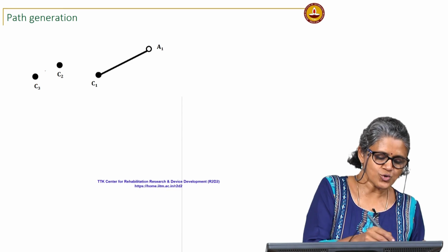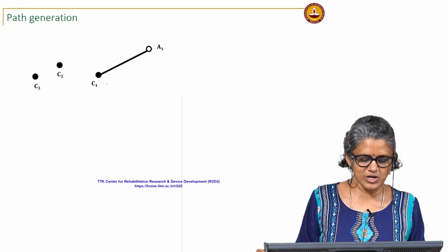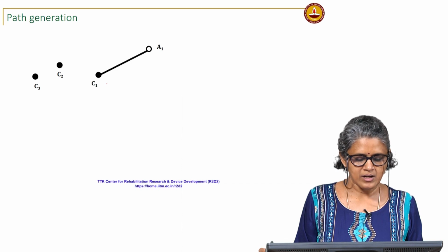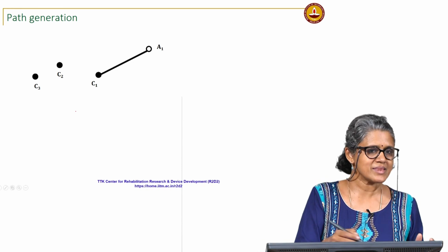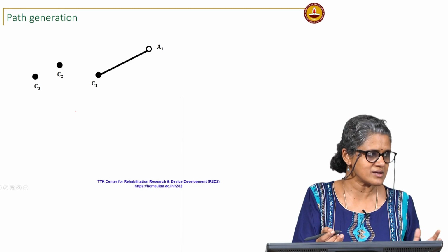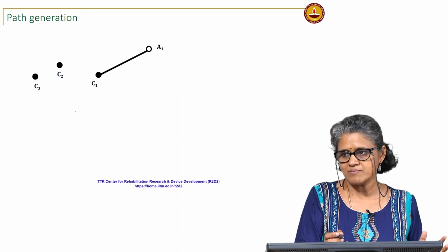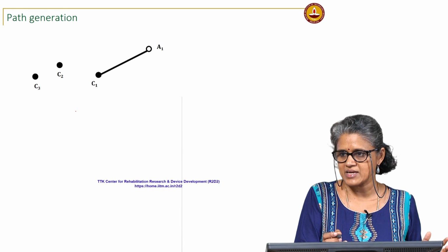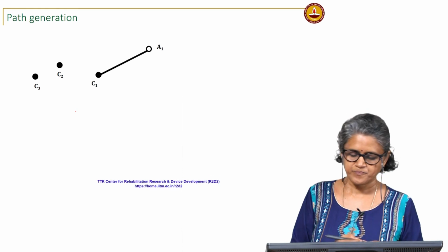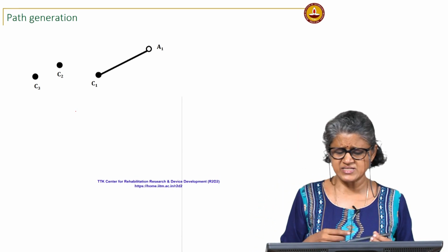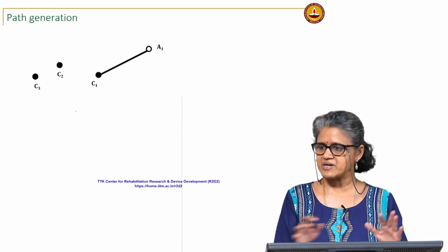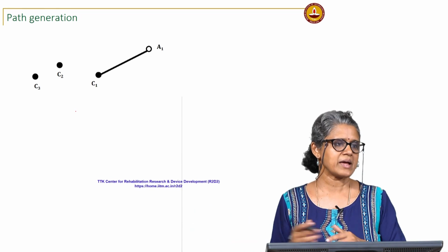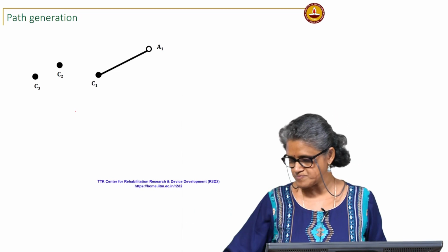So, you could have C as one of the moving pivots, in which case you would do your typical construction, and then you choose A as another moving pivot and you can synthesize the linkage. Okay. So, path generation is fairly simple, and again limiting positions, driver dyad, the same things apply to all of these.